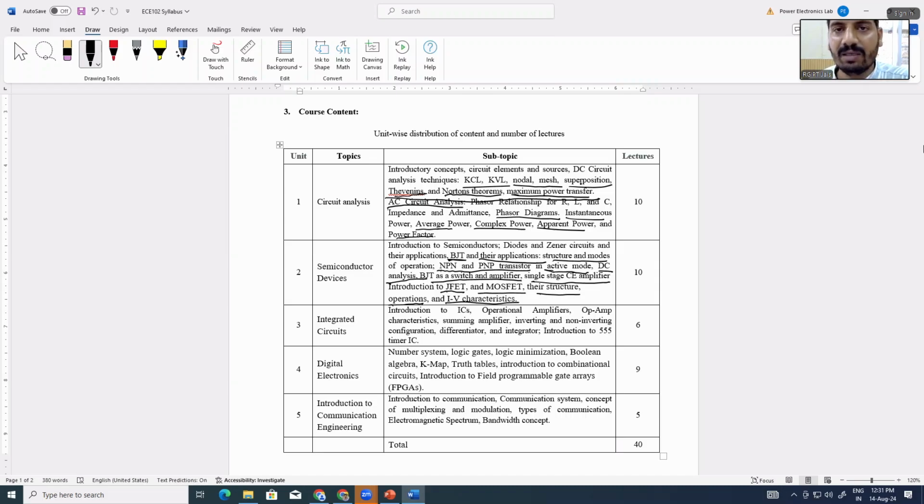So you'll have basic understanding about diodes and transistors. In transistors, BJT and field effect transistors are more common. The difference between BJT and field effect transistors, that is JFET and MOSFET, is that BJT is a bipolar device, whereas FET, the field effect transistor, is a unipolar device. Unipolar means it has either positive polarity or negative polarity based on the channel. In JFET and MOSFET, we use a channel, and the channel can be N-type or P-type.